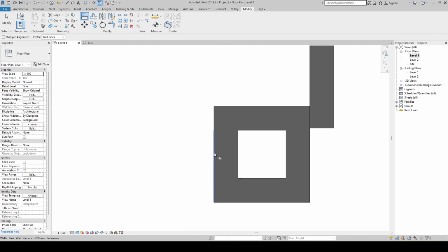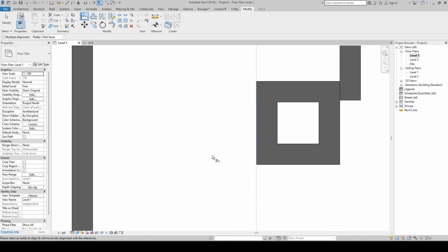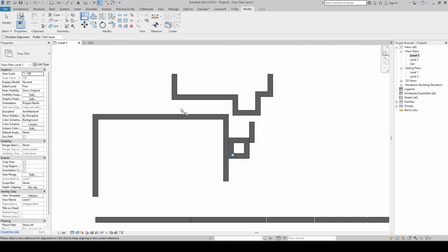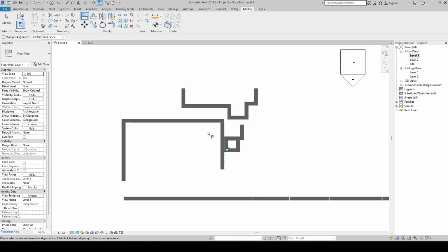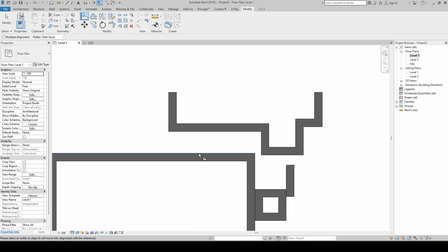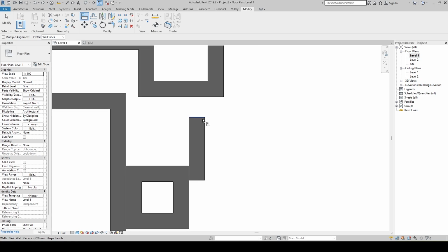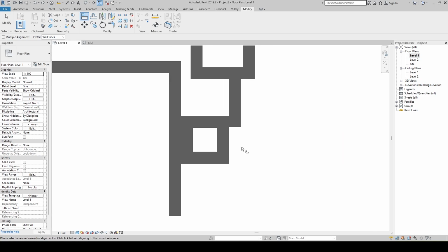Here as well, if you want, select the reference wall and then this wall. See, the wall has been aligned along with the extension of this wall. Then again, if you want, you can take this way and close this. See, this is how it works. I'm clicking Control Z. Then if you want, you can once again align this face with this one. So basically this is how the align option works.